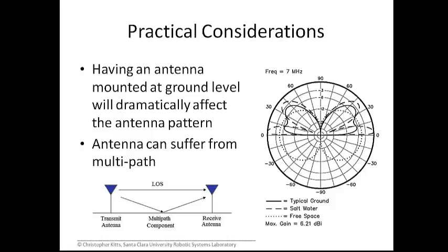So you really need to be aware of the surroundings when you mount an antenna. What's it attached to? What's immediately behind it? Is it something that is going to maybe improve or detract from the characteristics of the antenna in terms of its gain? Will it alter the beam pattern? If so, how? And so for those of you familiar with the installation on the roof, we have concerns about the fact that we have big HVAC units up there, and those are big metallic reflective kinds of surfaces, and how does that affect our beam patterns? That's a concern that we have for our own installation.